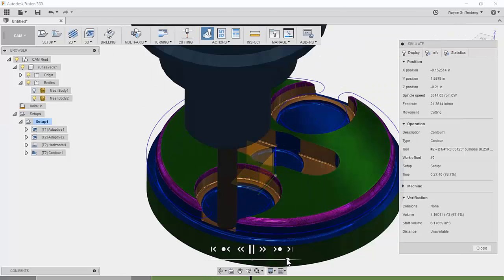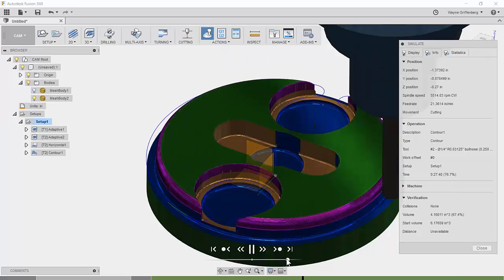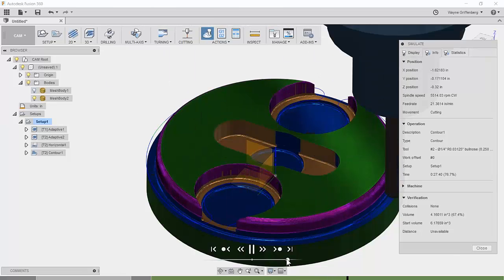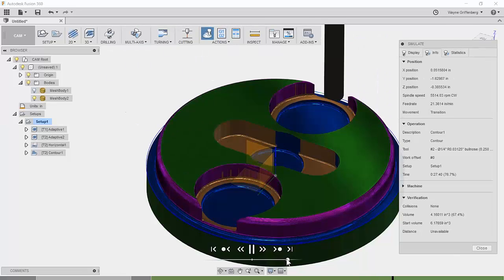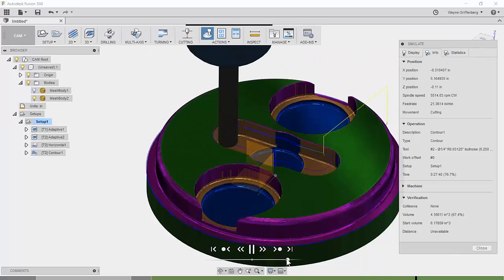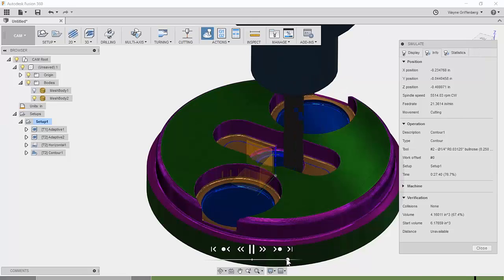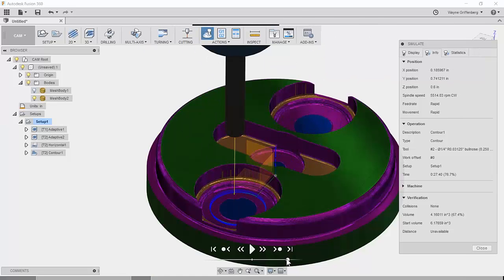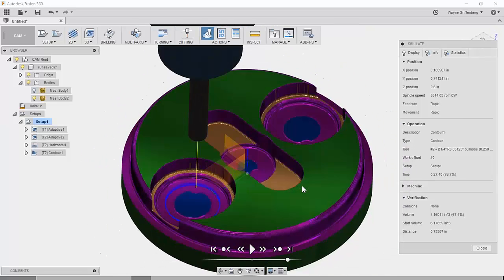So again, we're driving these toolpaths off of an STL model. We didn't have to create or even convert it to a solid. You can get your parts right off that STL model. You can get the code over to the machine, and you're going to have a pretty good, decent part. Now, of course, if you're trying to really drive it on the surface, you're trying to stay very precise, your model has to be precise to keep that precision in the part itself. But if you're not looking for that precision in this case, we're okay driving that off the STL model.